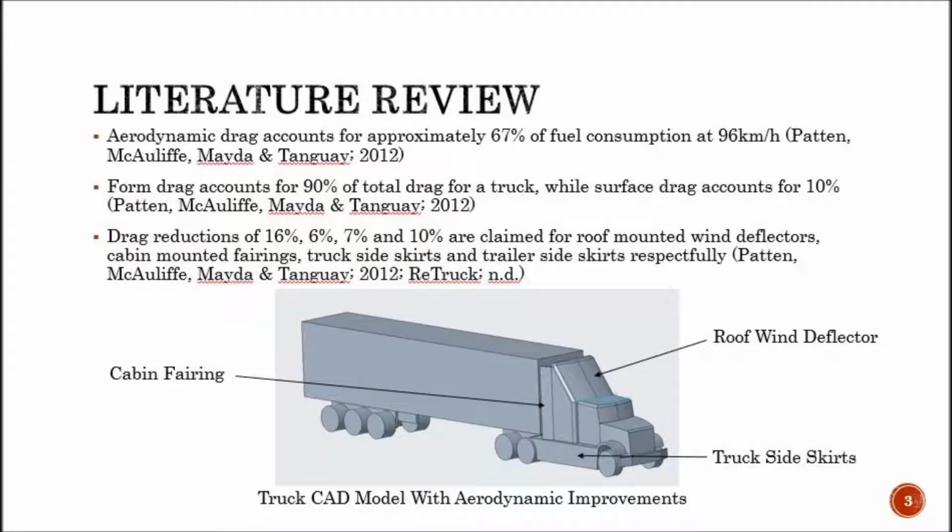Aerodynamic drag is proportional to speed and can account for 33% of total fuel consumption for trucks travelling at 53 km per hour, but increases to 50% at 80 km per hour. In addition to this, for trucks travelling at 96 km per hour, aerodynamic drag accounts for approximately 62% of total fuel consumption. In the case of a truck, form drag accounts for approximately 90% of the truck's aerodynamic drag, whereas the